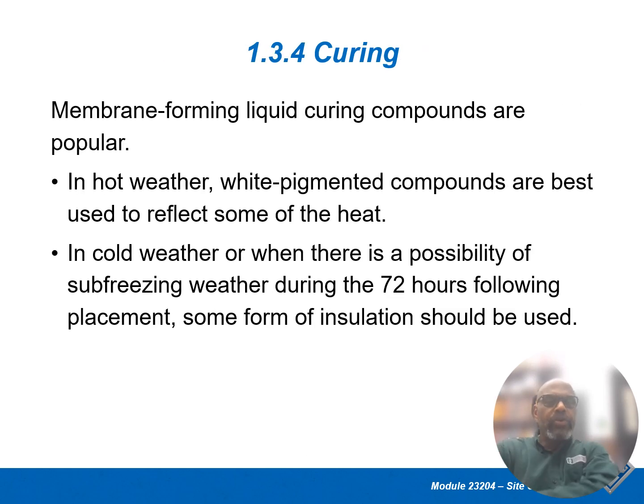Curing. Membrane-forming liquid curing compounds are popular. In hot weather, white pigment compounds are best used to reflect some of the heat away. I don't know if you've ever seen that before. Maybe I could do a video on that.